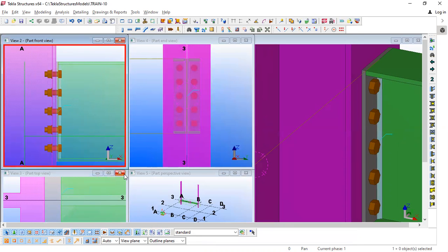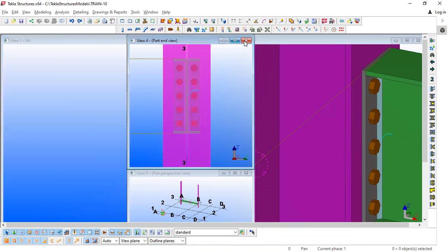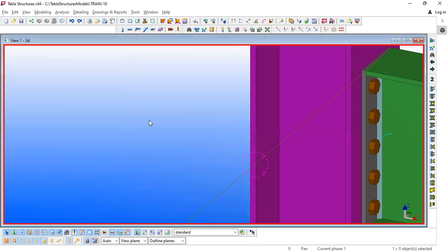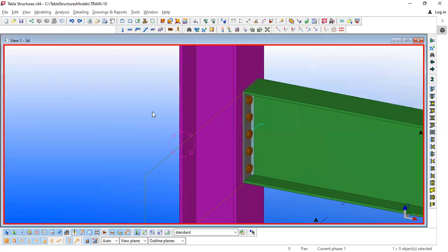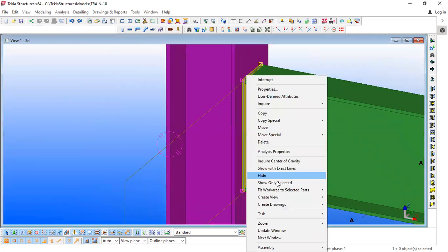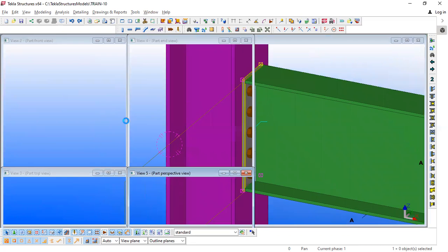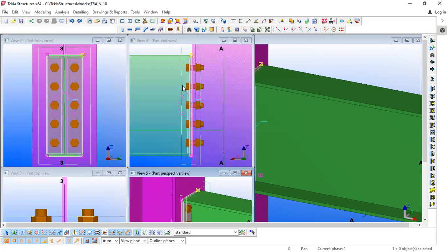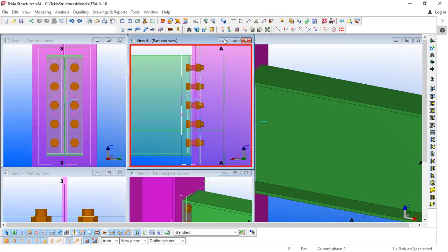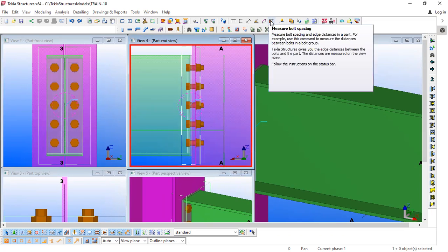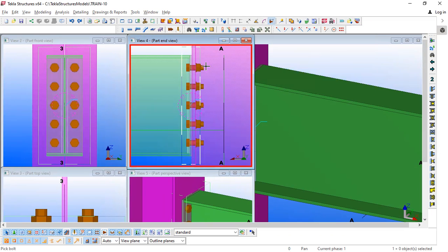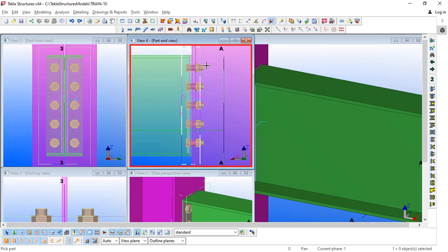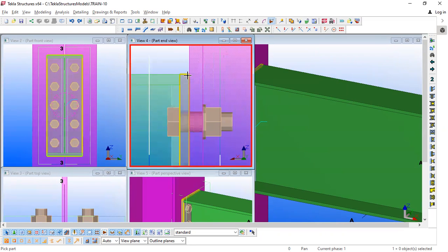So today we saw how manually we are going to add the bolts and all those things. We can check the spacings, can verify the pitch and everything of this bolt. How? We have an option here, measure bolt, right? I'll just click on this bolt. Okay, click on this option, select the bolt and select any part which you want to measure. So say I will say plate.